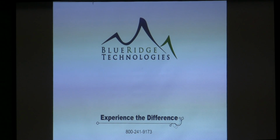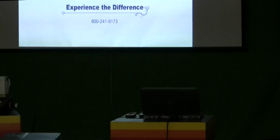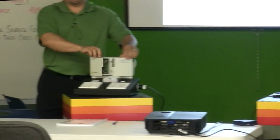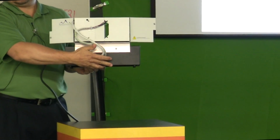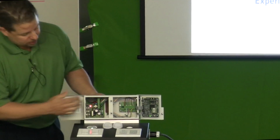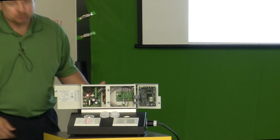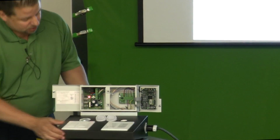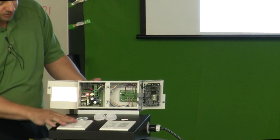So I'm going to switch gears now, and we'll talk a little bit about the demo unit I have here. Can everybody see this all right? So this module mounts to, like I said, a 4-square junction box. Once you've done that, the line voltage compartment is here, and that's where the wires come through, or you can see my fingers here. That's where the wires come through for the line voltage section. That's the terminal block that I showed you on the PowerPoint earlier for the line, neutral, ground, the 2 switches.